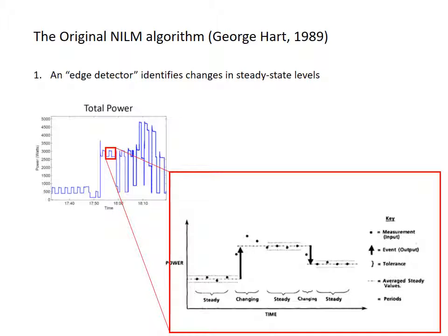But it has obviously advanced quite a bit beyond this. What I'm going to show you today is really the first, most important non-intrusive load monitoring technique, and I'm hoping you will realize that the field has advanced quite a bit beyond this today. So let's say we have this total power signature that's shown in this blue diagram over on the top left. What we really want is an algorithm that identifies anytime we experience a step change, and that's zoomed in here in the figure in the bottom right.